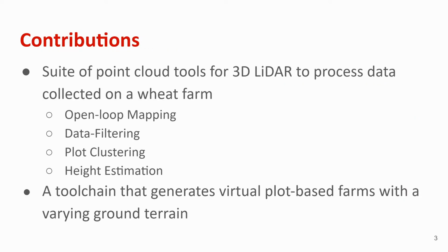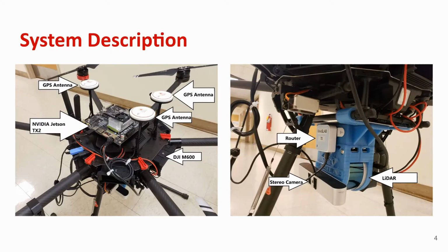Our work has two main contributions. The first is a suite of point cloud tools for use with a 3D LiDAR sensor to process data. We also created a tool chain to generate virtual plot-based farms that have a varying ground terrain that can be manipulated with parameters. Our UAV frame was the DJI M600 Pro.